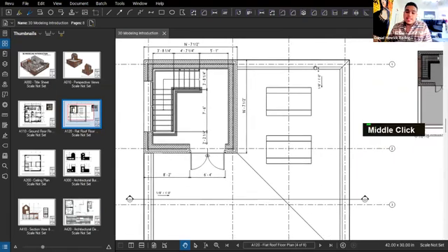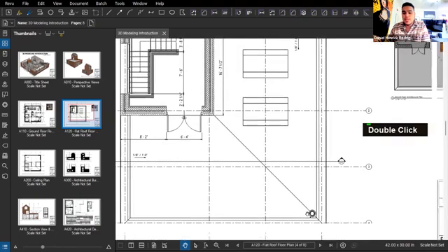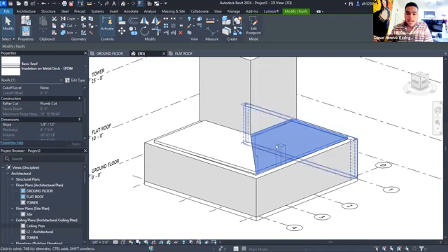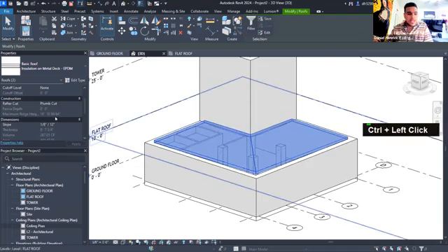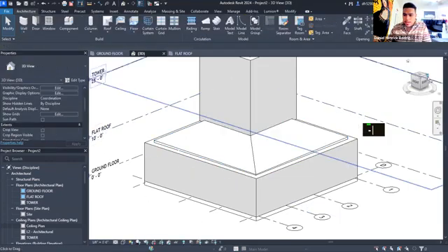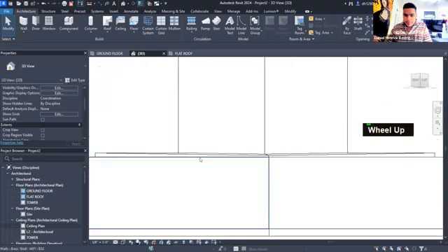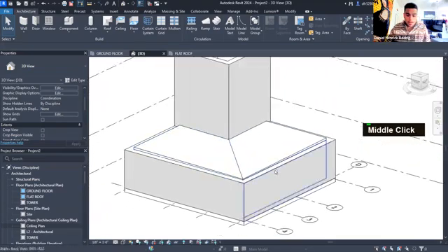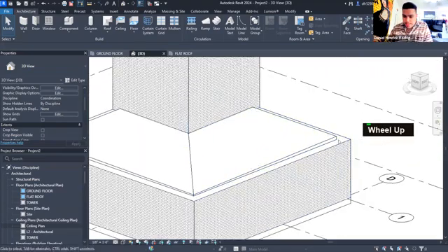And that's because this does slope towards the center here, because like I just showed you guys before, if you put down a roof and you have slopes, it goes up. So we want the negative for it to actually drain the water, right? So let's go back to our Revit here. I'm just gonna hit Control to select both. And all I'm gonna do here, I'm just gonna click in front of this symbol and put a negative there. And now our roof actually slopes to the center. Good, there we go. Okay, we have the sloped roof, but obviously it's above the wall.